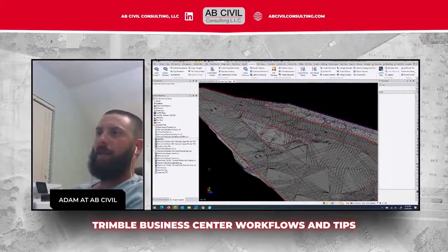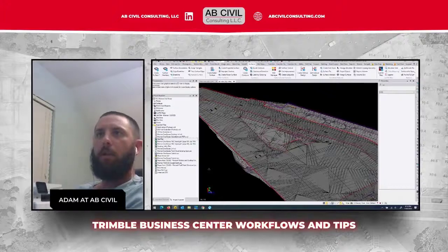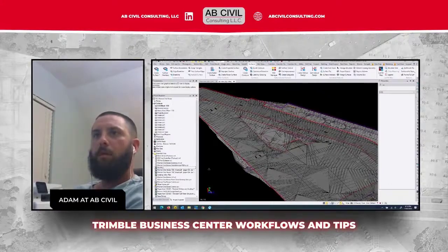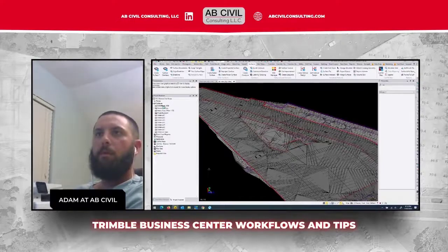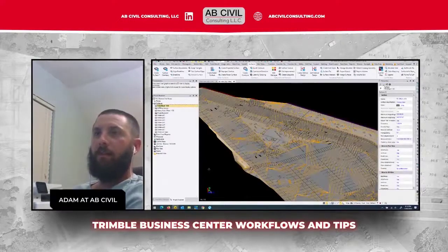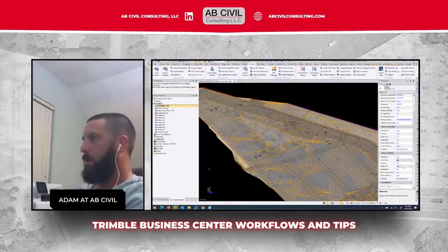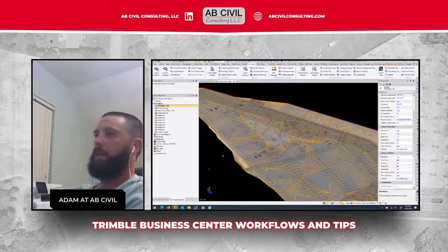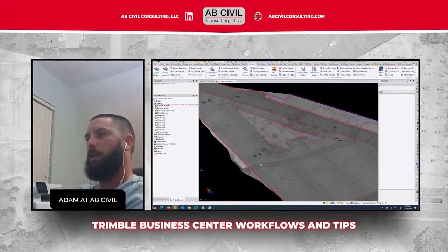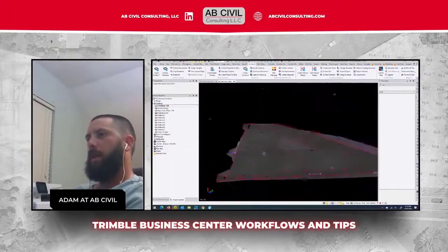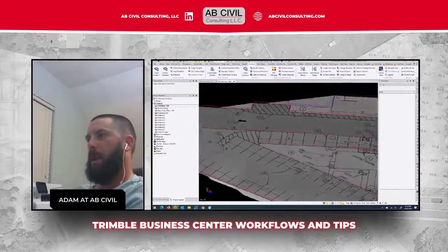The only thing is I don't really need any of these triangles on here. It just makes it look busy. So in here, same thing in Project Explorer. I click on this surface, FD offset minus 1.33. So show in 3D view, wireframe, no. Break lines, no. And I'm going to leave show shadows on. Yes, it makes it a little bit dimmer depending on where it's looking. So now that is a 3D view with the plan sheet dropped on top of it.